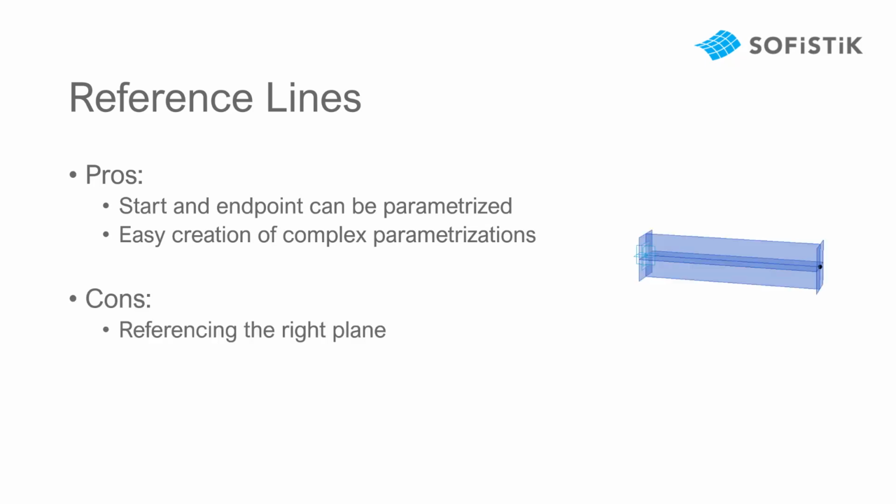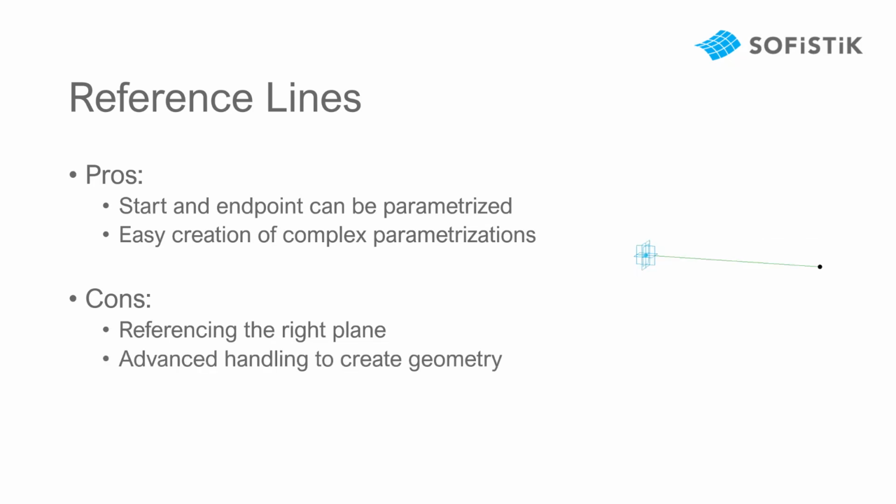The cons, on the other hand, are you need to keep in mind which reference plane you're right now working in, because both the start and end point, as well as the reference line itself, have reference planes that will be prioritized while creating new points. And it's advanced handling to create your geometry.